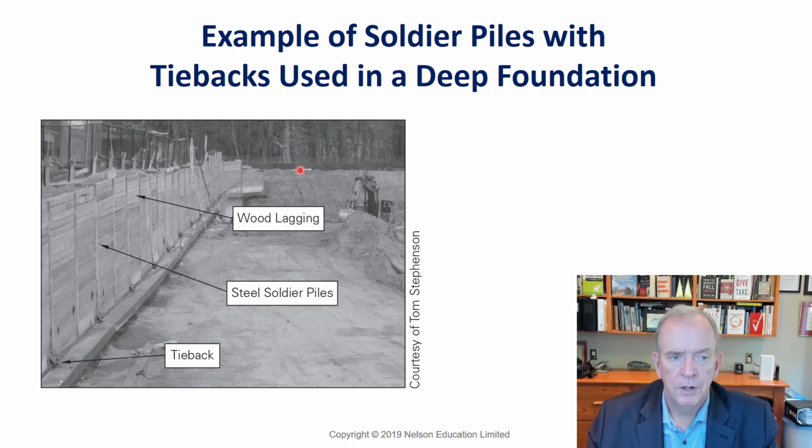There's your soldier piles. This was for a condominium project down near Eglinton and Bayview, near Sunnybrook Hospital, multi stories. You can see the piles, you can see the lagging, and you can see the tiebacks. These are drilled into the side, and then there's a crossover beam that's put in place to, again, support and transfer the lateral load, because this is going to continue to go down. You can see the excavator, it's going down multi-levels because it's a very large condominium. I think it had like 3 levels of underground parking when it was complete.